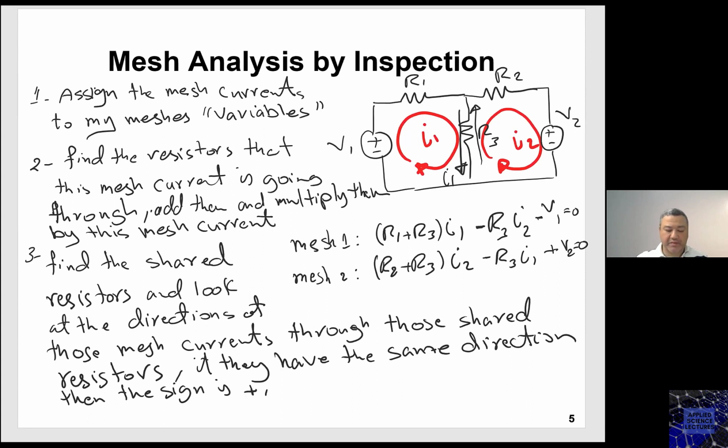Sure. Yes. Is it okay if we use a slightly different convention, but it turns out to be correct anyway? Like I typically use a voltage source as positive and you subtract a voltage across each resistor because it's a drop. So instead you could say V1 minus I1R1 minus I1R3 minus negative I2R3 equals 0.